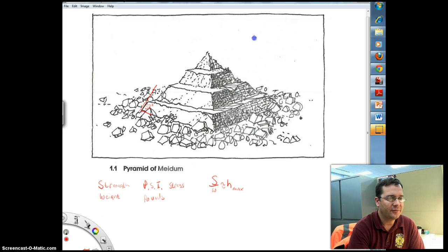Basically, the story is that if you started this pyramid with a block of some weight, well, then think about the blocks kind of below it. The blocks below have to support not only their own weight, but the weight of the block on top. And the blocks below them have to support the weight of the materials above them. And so it turns out that each successive layer of this pyramid has to get wider to have enough surface area available to support the weight above it.